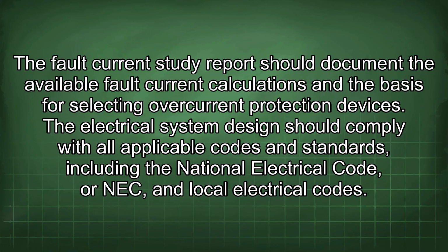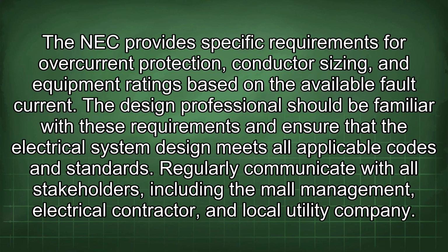The electrical system design should comply with all applicable codes and standards, including the National Electrical Code, or NEC, and local electrical codes. The NEC provides specific requirements for overcurrent protection, conductor sizing, and equipment ratings based on the available fault current. The design professional should be familiar with these requirements and ensure that the electrical system design meets all applicable codes and standards. Regularly communicate with all stakeholders, including the mall management, electrical contractor, and local utility company.